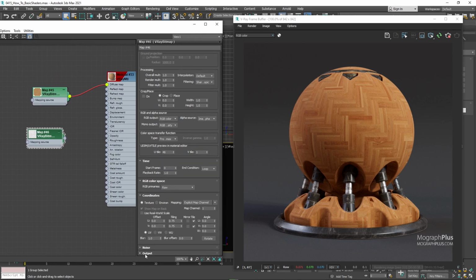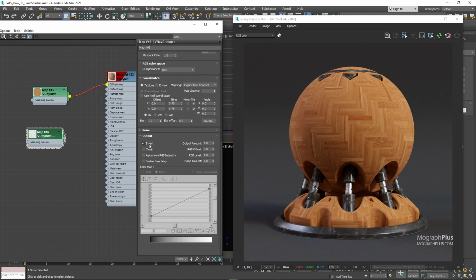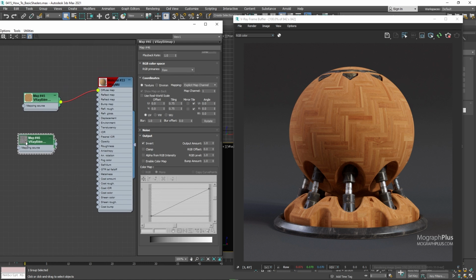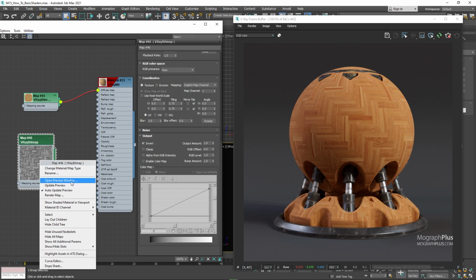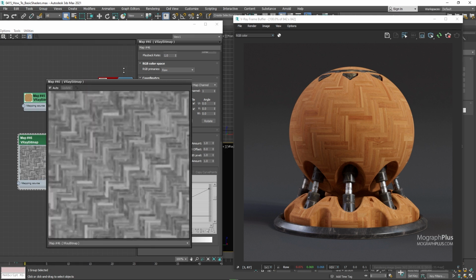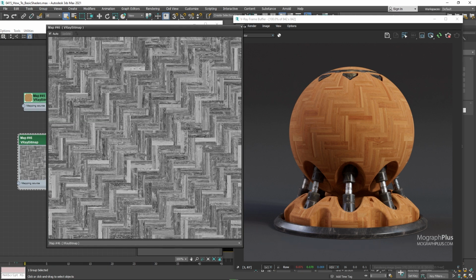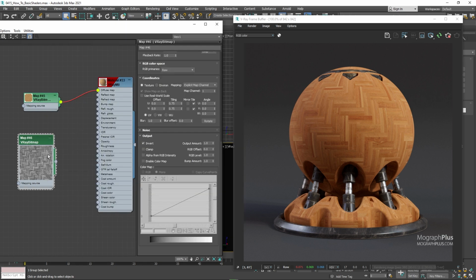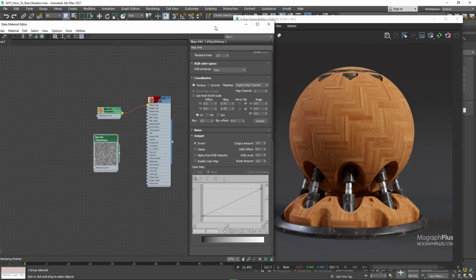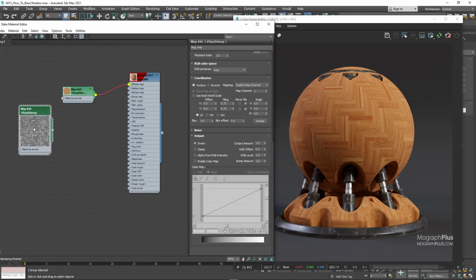And another suggestion to Chaos Group, just use the roughness map like any other modern workflow and ditch the glossiness value. Just replace it completely and be done with it. We can connect it directly to the reflection roughness input, or like the plastic shader, let's put it through an output map for further adjustments. So connect the roughness texture to an output map.